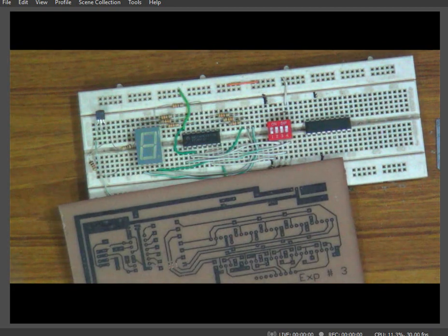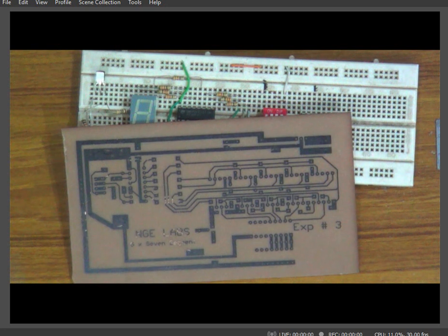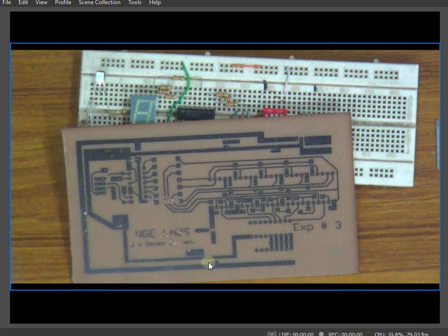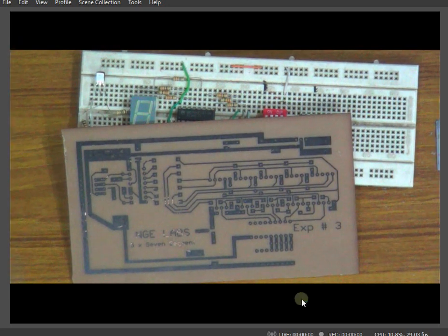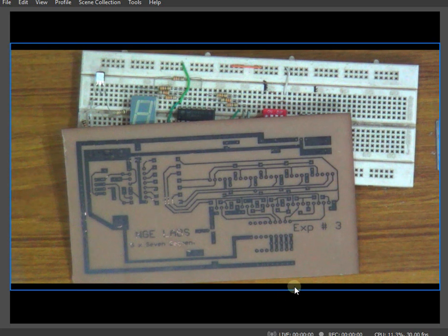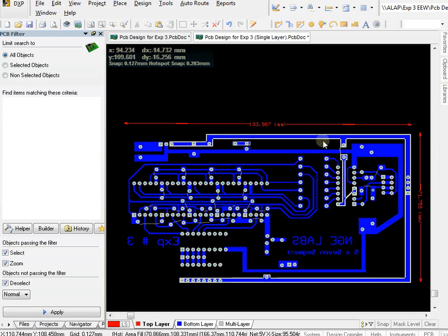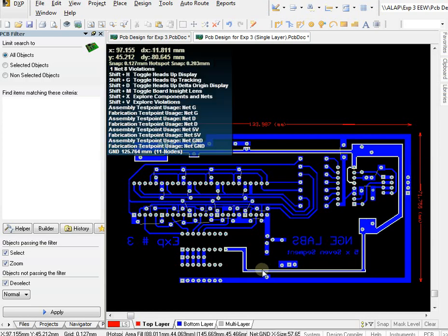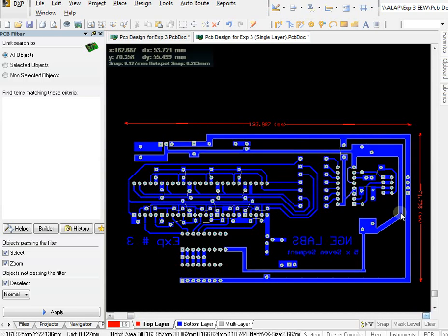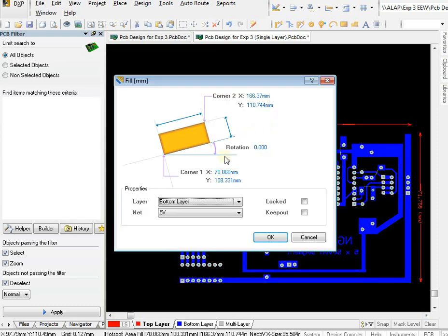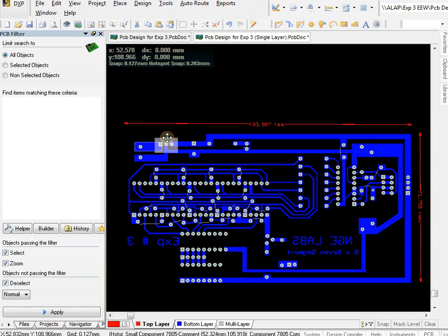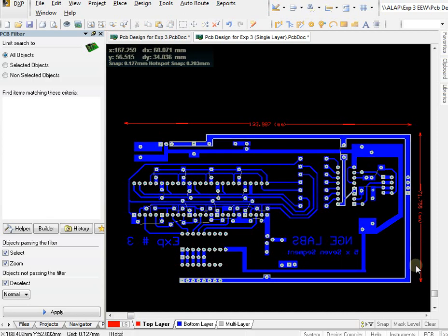I leave that black ink so that it does not erode, because copper corrodes very easily and can erode off very easily. Plus, one very important thing, please see, I have still made the fill areas. Fill areas are huge over there. You can see the fill areas are approximately very thick, because they are taking a large amount of current and carrying the whole 5 volt towards everything.